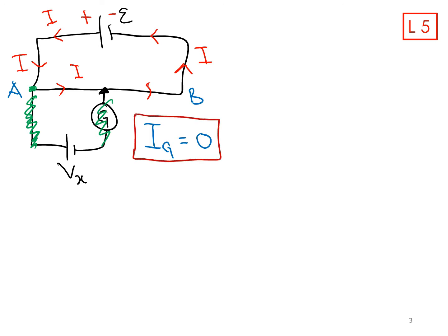Current across galvanometer equals 0. And this is when potentiometer is in balance. That's why we need to make sure it is in balance. Then you can calculate the values. If it is unbalanced, you cannot determine the potential difference. So the clue is make sure you know the concept: make sure it is in balance.